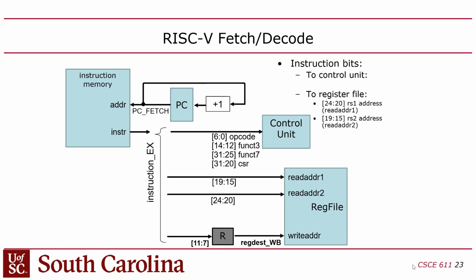You can decide how you want to do the control unit. But essentially, it's going to be some kind of if-then-else, case statement, whatever. It essentially just looks at those inputs and resolves them to control. Now you might say, wait a second, you don't have any outputs on that thing. Not yet. I'll show them in a minute. Right now it's just inputs. I'm just showing what inputs go in. But basically it's a lookup table that takes inputs and spits out the relevant signals.